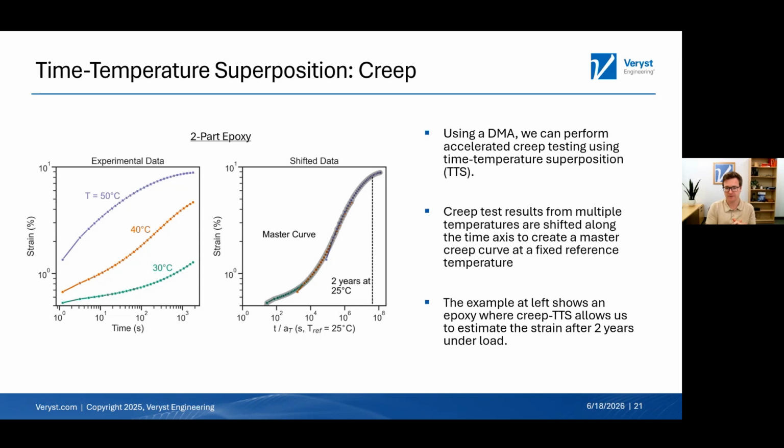And so depending on how certain we need to be about the performance, or how risky it is for this failure mode to be, we'll do the TTS testing in conjunction with real-time creep tests. And so we get an immediate answer that allows us to interrogate our design while getting that longer term validation that's real time, that doesn't rely on any accelerated testing.